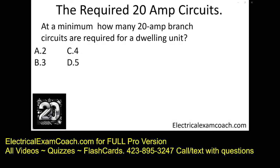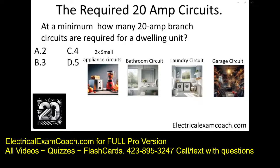At a minimum, how many 20 amp branch circuits are required for a dwelling unit? Now, this is asking a very specific question. There is a code minimum of 20 amp branch circuits that are required in every dwelling unit. The correct answer to this is 5. It's going to include our 2 small appliance circuits, our bathroom circuit, our laundry circuit, and our garage circuit. Now, this is not to be confused with the type questions that are asking about general or lighting or receptacle circuits. These are the code minimum of the required 20 amp branch circuits in a dwelling. And the answer is 5.